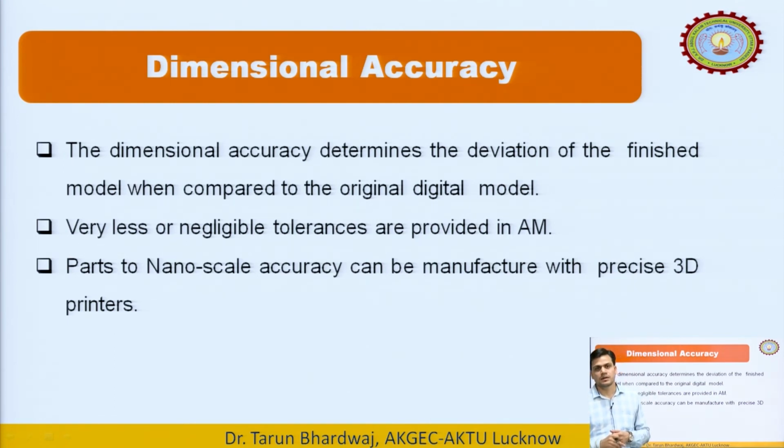Means अगर dimensional accuracy की मैं बात करूँ तो accuracy is basically nothing but a layer of this additive manufacturing technique. मतलब जो हमारी layer होती है that is basically representing dimensional accuracy. जितनी fine वो layer होगी उतनी फाइन हमको एक्यूरेसी मिलेगी, जितनी वो थिक होगी लेयर that will not be accurate, मीन्स the product जो होगा आपका वो एक्यूरेट नहीं बनेगा, ठीक है.